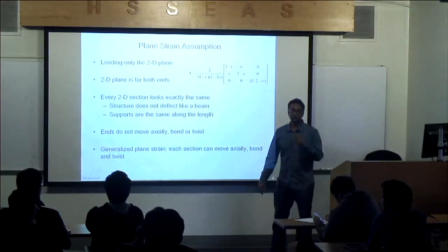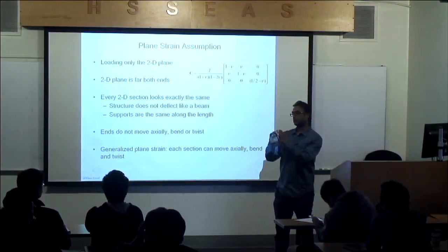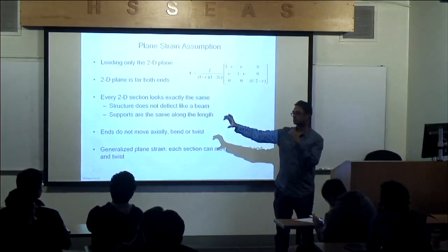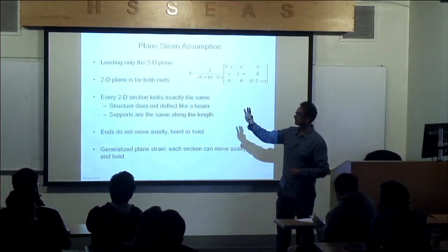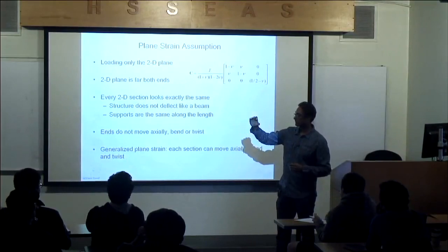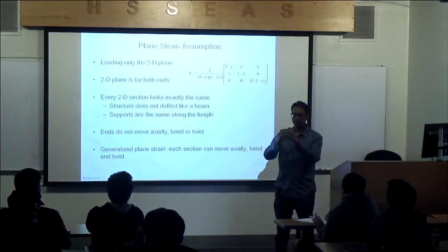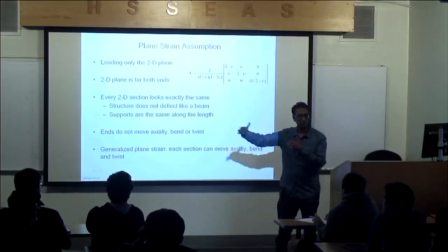An example is, take a pressure vessel and say the pressure vessel is about 20 feet long, but it's about this size, right? I'm just making an example. Then I can take that cross-section and just model that, because it's so long that, if I'm looking at stresses in that plane, you could basically assume they are the same all the way through.